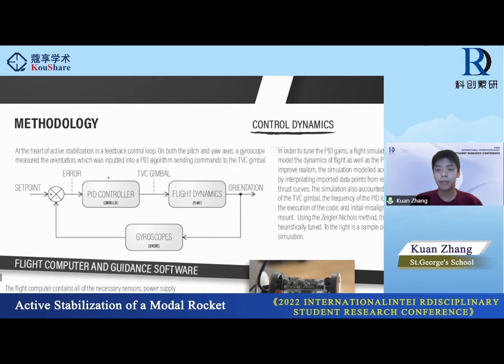The PID controller has three parts: a proportional response, an integral response, and a derivative response. The proportional response generates the actual feedback response to the error. The integral response corrects for the steady state error, and the derivative response accounts for the rate of change of the outputs. All in all, it's a pretty well-rounded algorithm, but it does require extensive tuning.